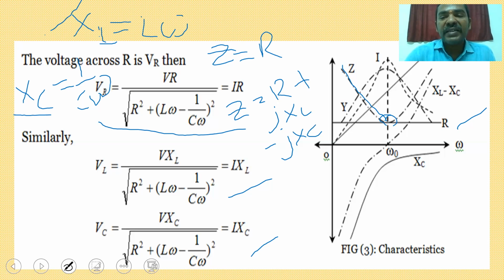After that, with further increase in omega, the circuit acts as an RL circuit, meaning the inductance is more compared with the capacitance. The admittance is quite the inverse. Initially it is minimum, you get the maximum at resonance, and then it falls down again. It is similar to the current: the maximum value is at resonance, and after that it gradually decreases with the change in frequency omega.